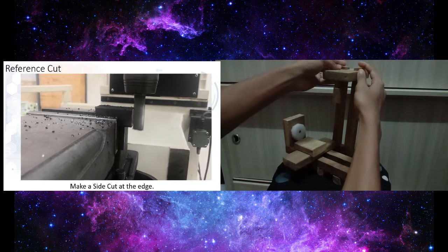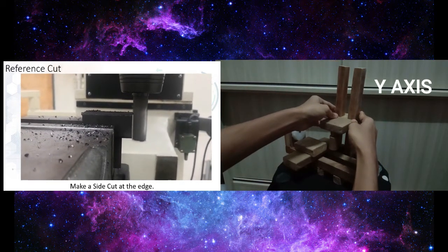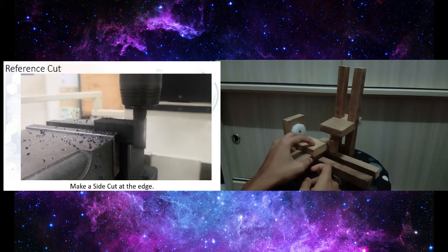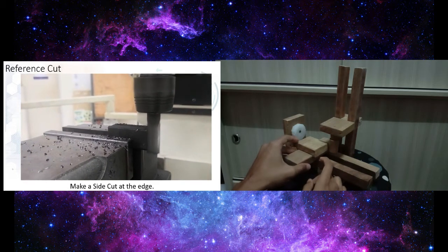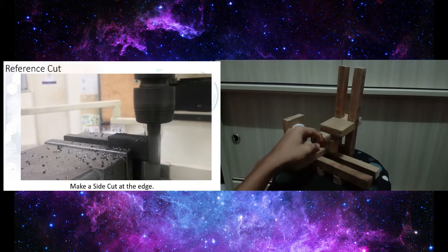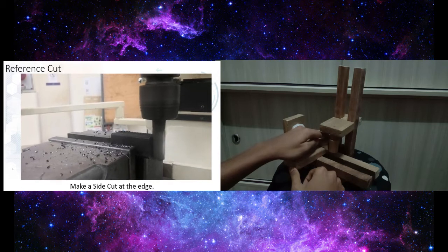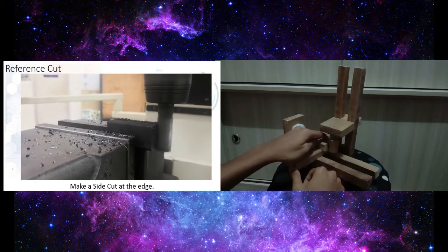After finishing the facing cut, we will move to the side cut. For the side cut, we will move the Z axis to go lower. Make sure the drill is at the same level as the surface of the material. Then we will move the X axis, so the surface will touch the drill, and then we will move the Y axis slowly to start the side cut.